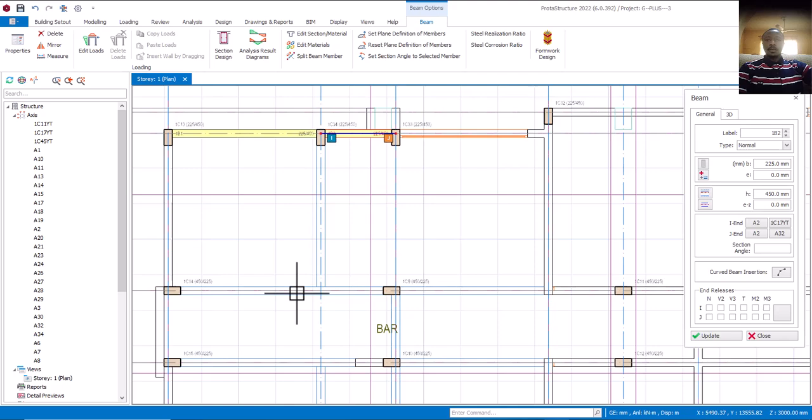So right click and measure. Let me measure from this point to this point. What is it? 450. Is that okay? We have 450. So escape. If it's 450, that means from here now, right click, I need something like, let me come in, offset it. 450 will be what? 225. Am I correct? So F2 and then 225. Enter. Okay, I have it here now.